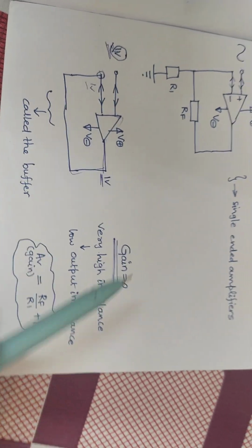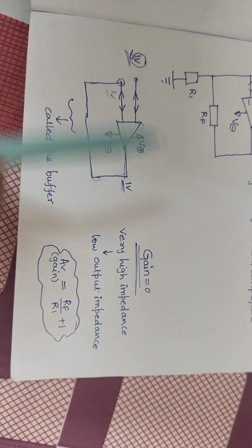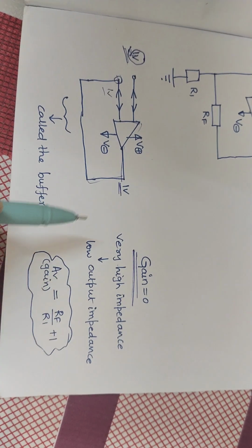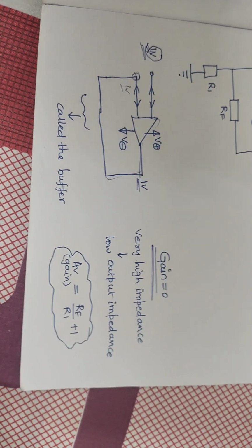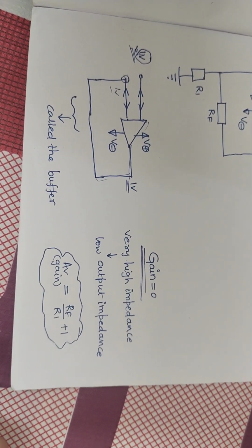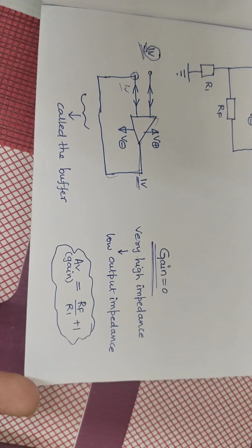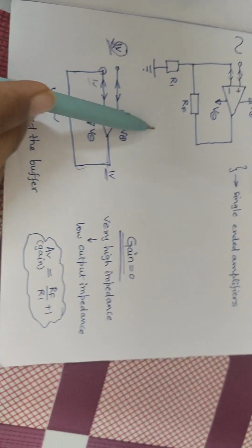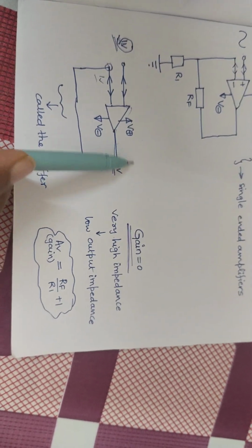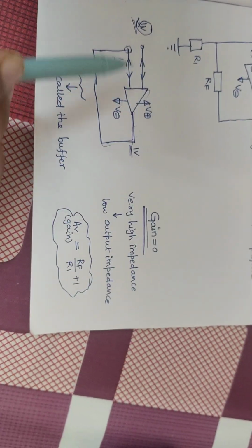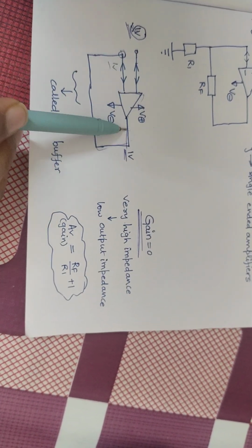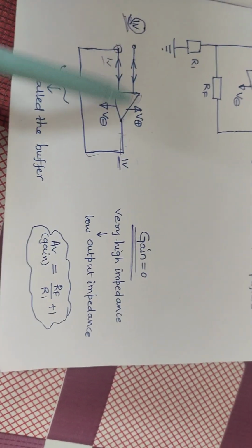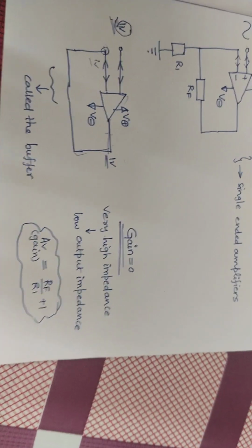Rule number 1 means no current flows through any load across the non-inverting input, like some sort of sensor, or a pulse-modulated signal from a microcontroller with a low pass filter, or whatever it is. No current goes into the operational amplifier, so it doesn't disturb the sensor or circuit. You can observe the input works as a very high input impedance, and the output works as a very low output impedance. It can drive things from a very sensitive input.